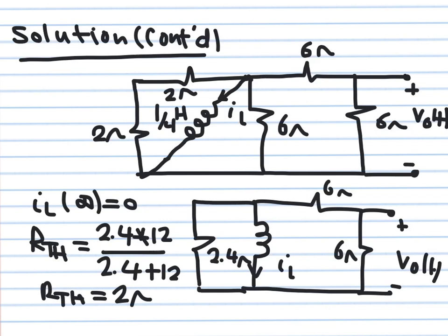Of course, if you take a look at what's happening, this one has some initial current, and this current has been established from stage 1 when the battery was there. After the battery is removed, the inductor will start to supply power to all these resistances, and gradually and slowly it's going to lose all its energy. So we know that at infinity, there will be no current in the inductor. Okay, it's going to be completely discharged. It lost its magnetic field completely.